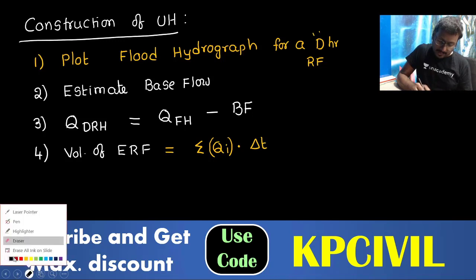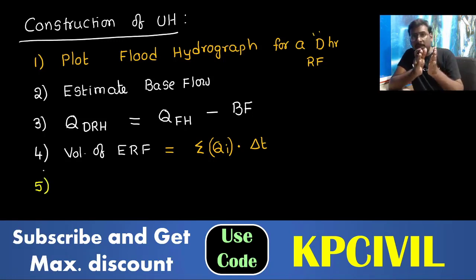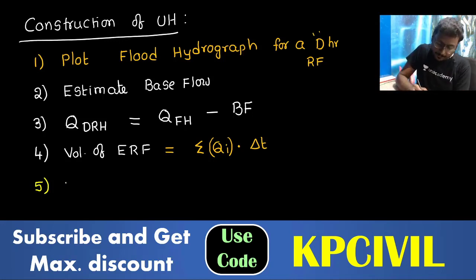So each discharge value multiplied with change in time. Sum of Q1 plus Q2 plus Q3 of direct runoff ordinates, into difference in time, that is taken as volume of effective rainfall.